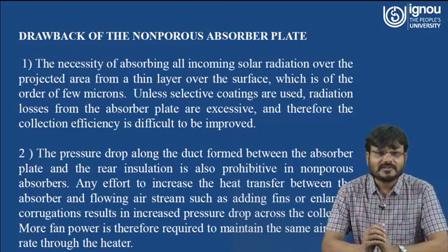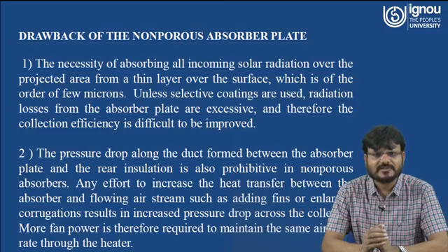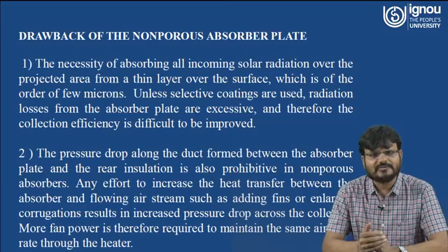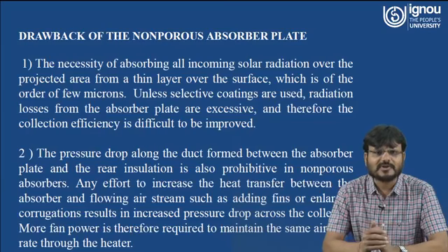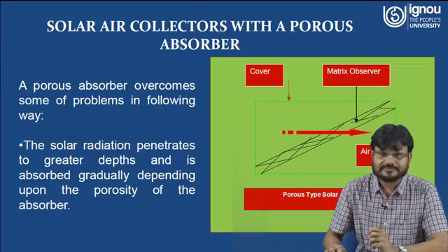Another drawback is what? The pressure drop along the duct formed between the absorber plate and the rear insulation is also prohibitive in a non-porous absorber. Any effort to increase the heat transfer between the absorber and the flowing air stream, such as adding fins or enlarged corrugation, results in increased pressure drop across the collector. So what do you need? More fan power is therefore required to maintain the same airflow rate through the heater. So these two are the drawbacks of the non-porous absorber plate.